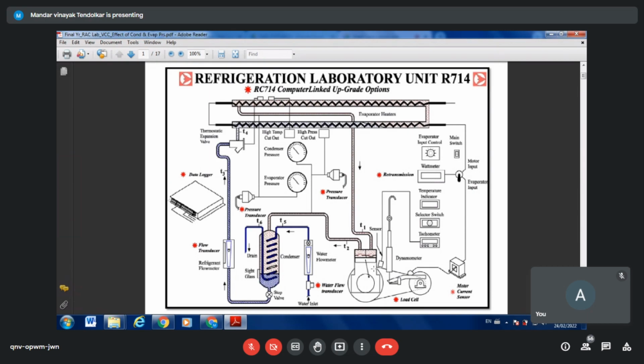Saturated vapor? Yeah, H3 is saturated liquid. Yes, sir. So, sir, saturated vapor कहाँ से आया? H3 is saturated liquid. So, sir, when it follows the throttling process, it will obviously fall in the middle of the dome. That is the saturated part, sir. No, that is two-phase, not saturated. Yeah, two-phase mixture. So, sir, by increasing that temperature, the path will only follow one way. How and why?